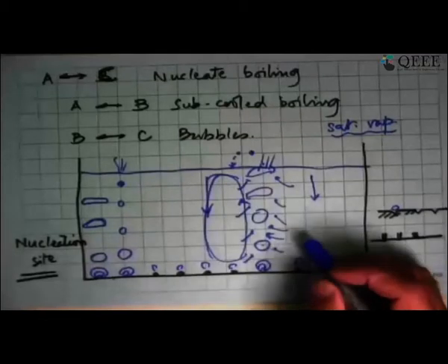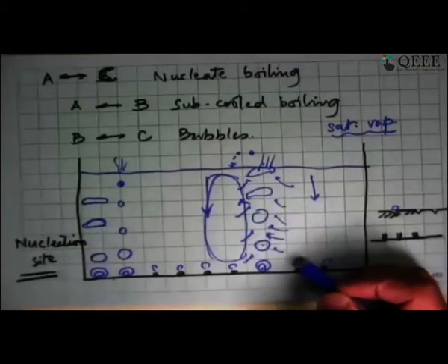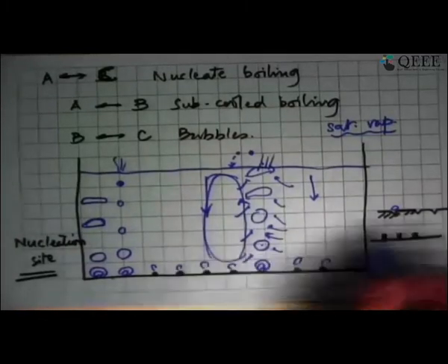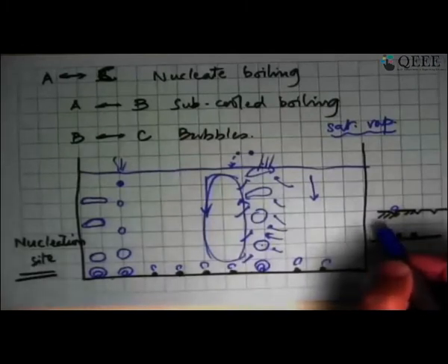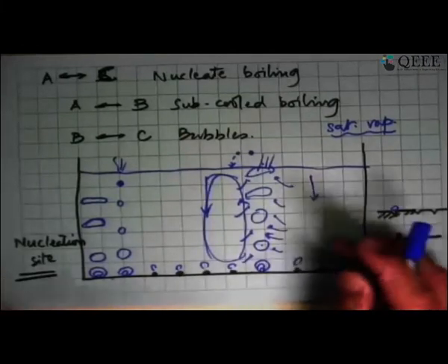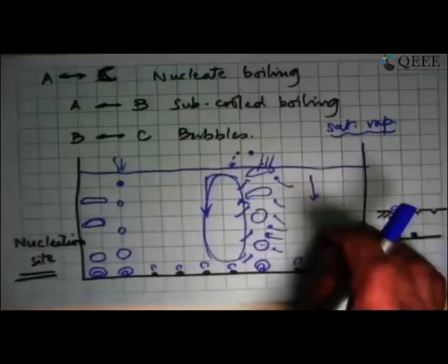And many of the tubes that we see these days in applications, refrigerators or even boilers, do have these features which enhance local boiling, and they encourage nucleation by artificially creating these nucleation sites. A practically manufactured surface has a certain roughness, but it is never 100% smooth, and over a period of time you gradually see these things happening.